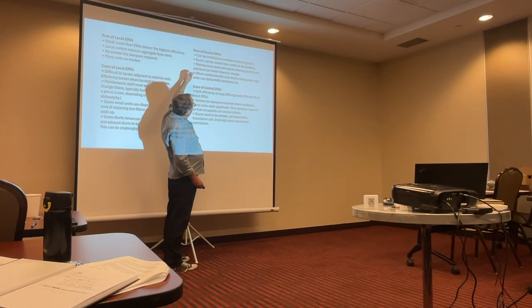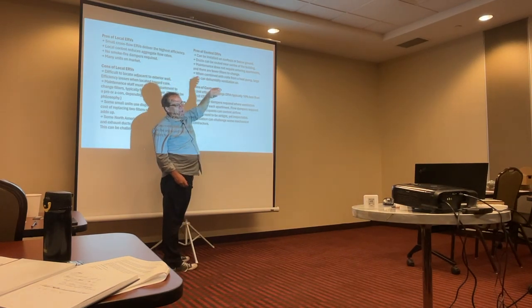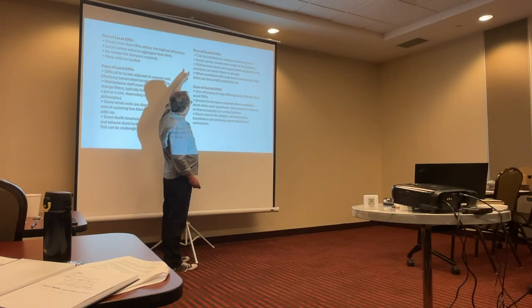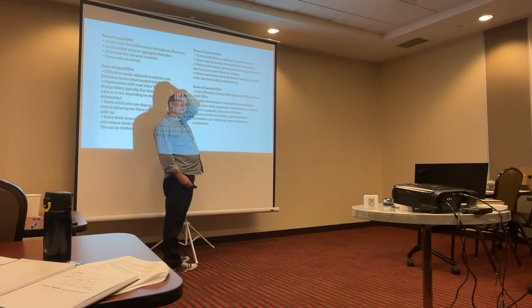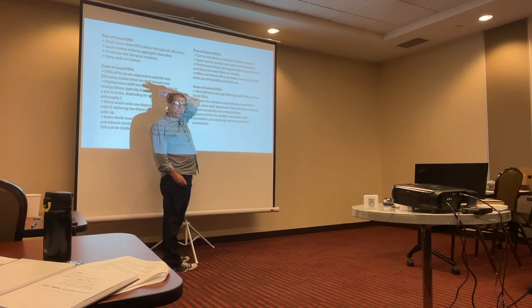Maintenance does not require entering apartments. There are fewer filters overall. Your annual maintenance and your emergency maintenance after each smoke event is way less. When combined with coils and a heat pump, they could dehumidify, which you really can't practically do locally. And the dehumidification issue is a big issue now. And realize that as our summers become warmer, they also become more humid. The two things go together.